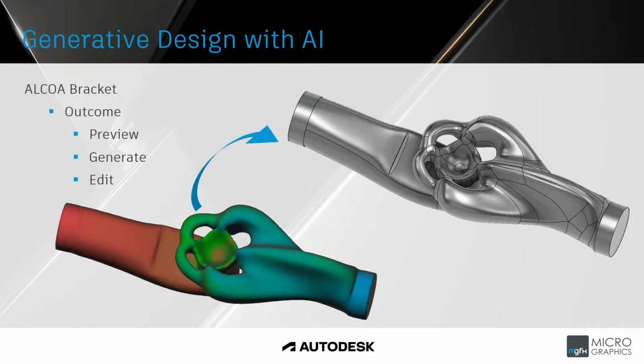And what we get here is the same type of geometry as the structural generative design. We get a solid component that is made up of the preserved geometry regions, but it represents the fluid flow region. So this represents the cavity within that valve. And this is also, once again, made up with those sculpt surfaces or those freeform surfaces. So you can go in and you can edit that freeform and you can adjust the geometry. Maybe you don't like this hard edge here, that step. You can delete that and blend it in, make it smoother.